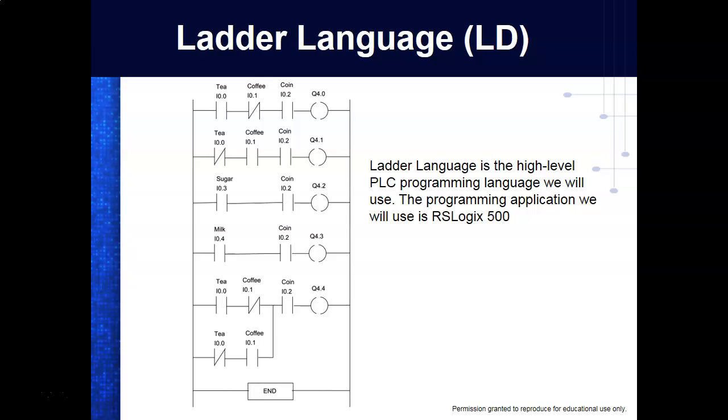This is the language. This is ladder language, and this basically came up through electrical. In motor controls, you will learn ladder diagrams. The way ladder diagrams work is we have two power rails, but in the PLC there's actually no power. These are all simulated. Then we draw circuits between them, and each one of these is referred to as a rung. You can see how it got that name, ladder. We draw circuits between this rail right here, which we generically refer to as L1, and this one right here, which we generically refer to as L2.